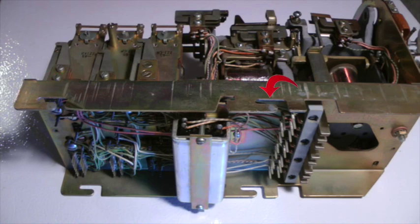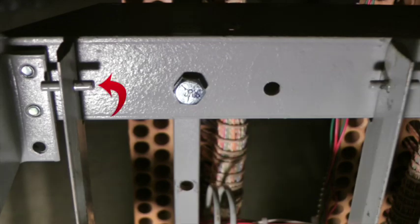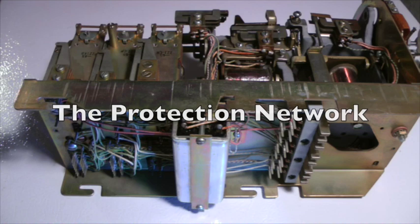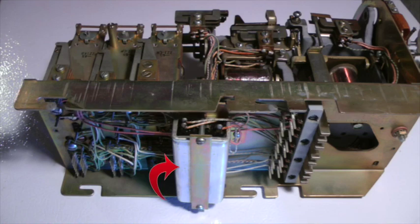Cut into the switch base plate are these 4 bayonet-style mounting slots. These slots slide over these 4 pins on the line finder mounting shelf that firmly hold the line finder in its fixed position. This rectangular metal can contains the A network, which is a protection network. It consists of 2 1 microfarad capacitors and a 160 ohm resistor. Its function is to prevent electrical arcing across contacts 1 and 2 of the C relay, which are used to energize and de-energize the vertical and rotary stepping magnets.